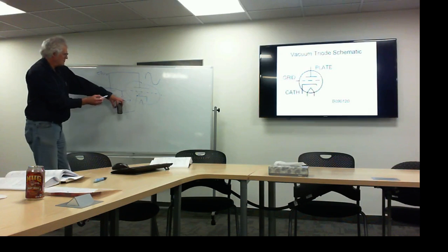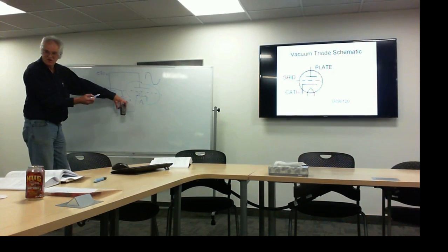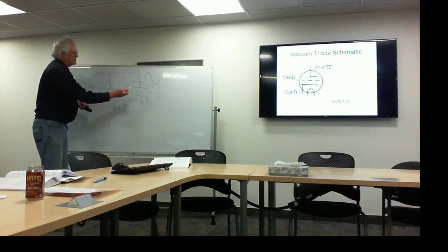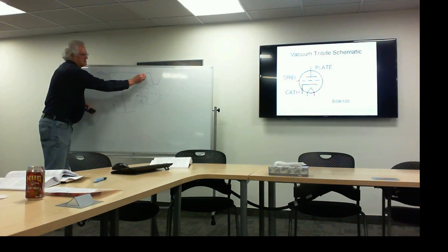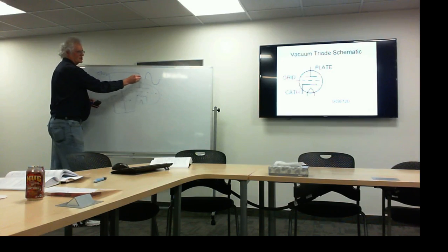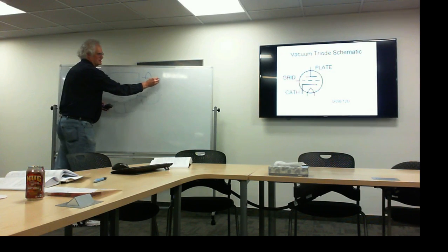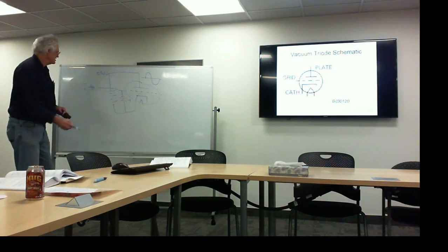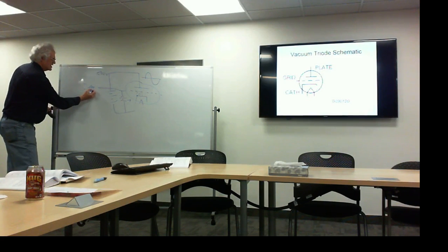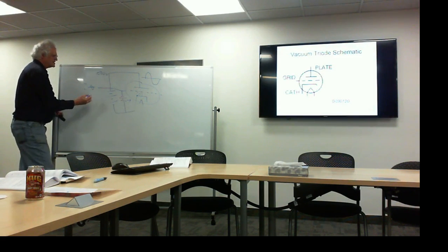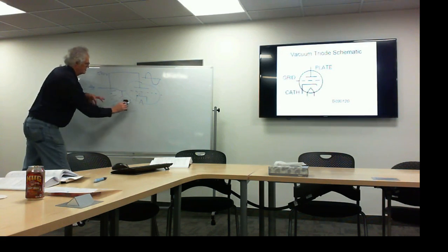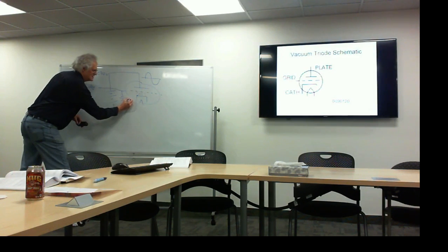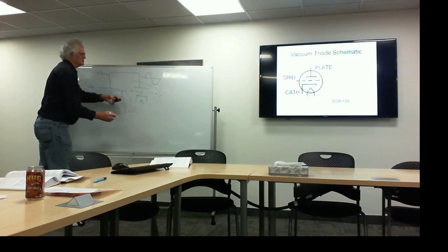Because we dropped that bias from -10 to -9, which is a smaller voltage, putting less control on it, we'll see the output have more current through it, an increase in the current flow. Likewise, at this point in time right here, we only have -1 volt, so we're going to increase that reverse bias to -11 volts.